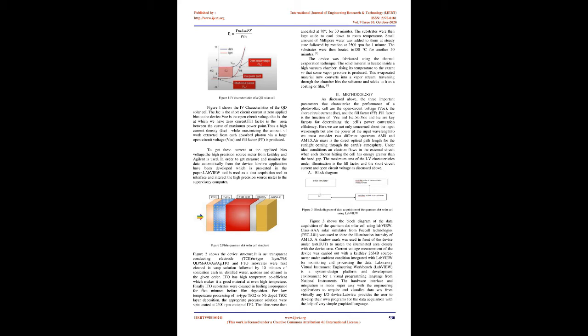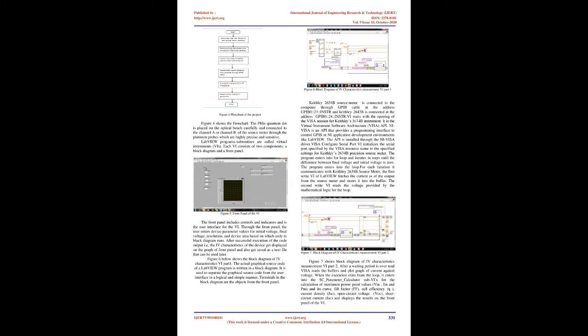The device was fabricated using the thermal evaporation technique. The solid material is heated inside a high vacuum chamber, raising its temperature to the extent that some vapor pressure is produced. This evaporated material now converts into a vapor stream, traverses through the chamber, hits the substrate and sticks to it as a coating or film.